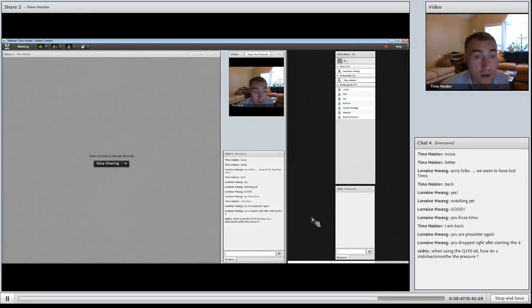Yes, I do. Okay, Cedric is asking, when using Q1 P0 elements, how do I stabilize the pressure? So, as you correctly point out, the Q1 P0 is not a stable element. So you get oscillating solutions. So my first answer would be, well, you wouldn't use that element. The question is, why do you want to use that element? So something you could use, for example, is Q2 P0, which is stable. You can just use that. You just change the parameter to use discontinuous pressure in the examples, and you can run this.